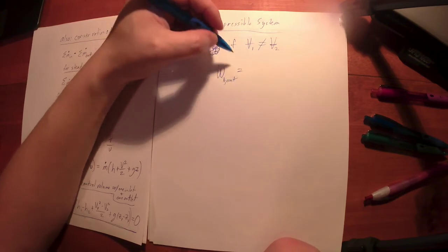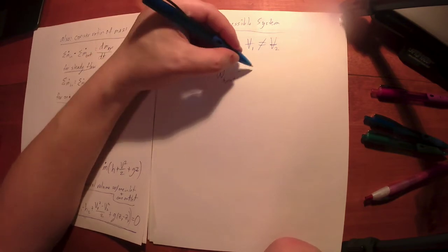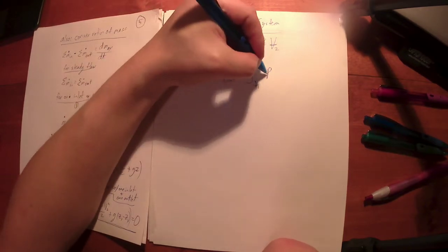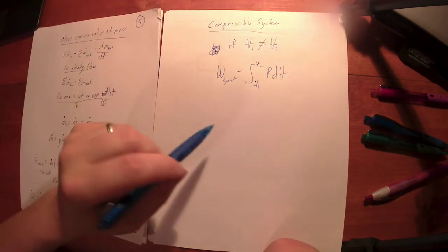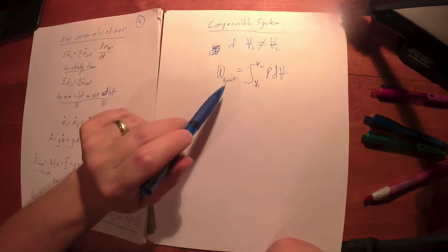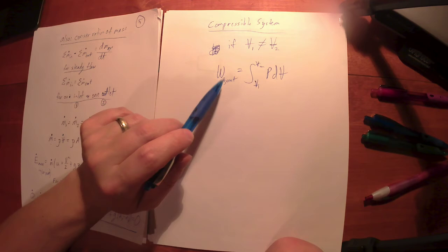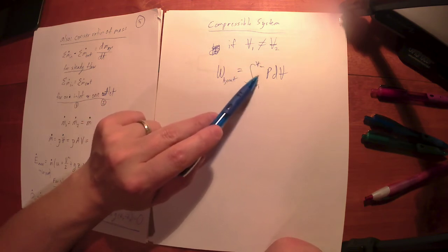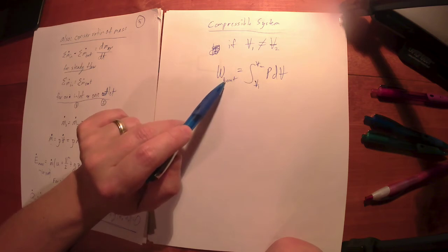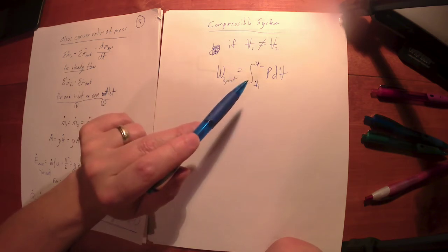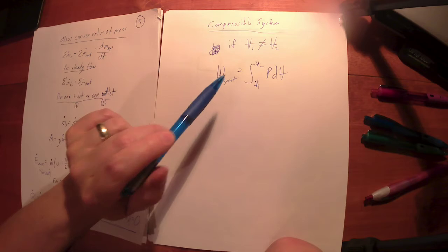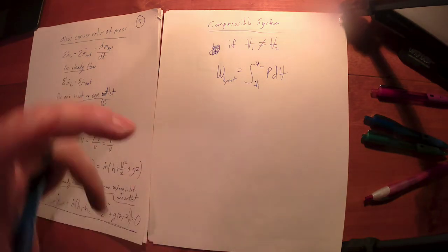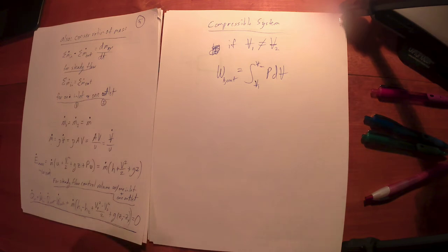And that work comes in the form of what we call the boundary work. If you integrate pressure with respect to volume from the initial volume to the final volume, you're measuring the work output. If you want to find the work input, the compression work, you need to switch the sign on the integral, or just understand that when I compute the work out, I'm going to get a negative quantity. So if I get a negative quantity here, it's just telling me that I'm actually compressing the system, I'm putting work into it. If the system's expanding, then it's putting work out.